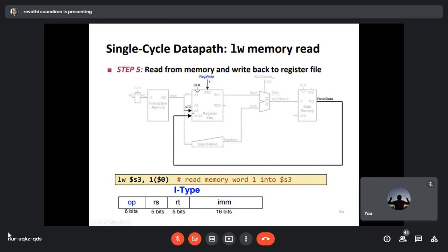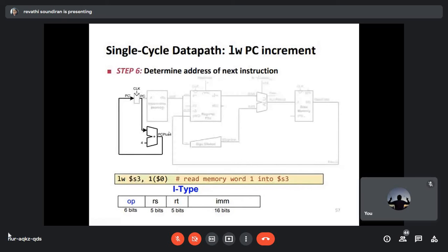So in this case, your current program counter address value is incremented by 4. Here is again an ALU operation taking place, so the addition of the value 4. It is being added, and the new program counter value is being stored here. So this is the location of the memory address. The generated value is the memory location of the next instruction to process.